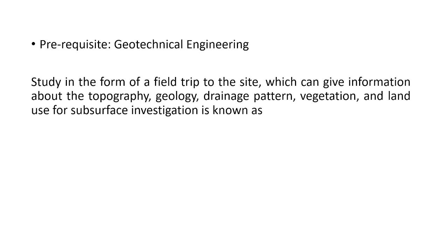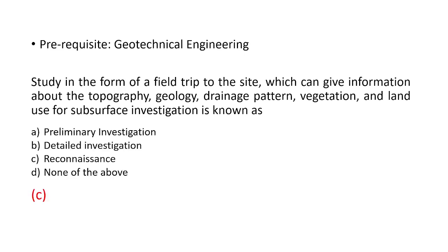Okay, so let's start. The first question is: a study in the form of a field trip to the site, which can give information about the topography, geology, drainage pattern, vegetation and land use for subsurface investigation, is known as. The options are preliminary investigation, detailed investigation, reconnaissance and none of the above. As we can see in the question, it is a study in the form of a field trip to the site which can give information about the topography, geology, drainage pattern, vegetation and land use. See, the first option is preliminary investigation, right?